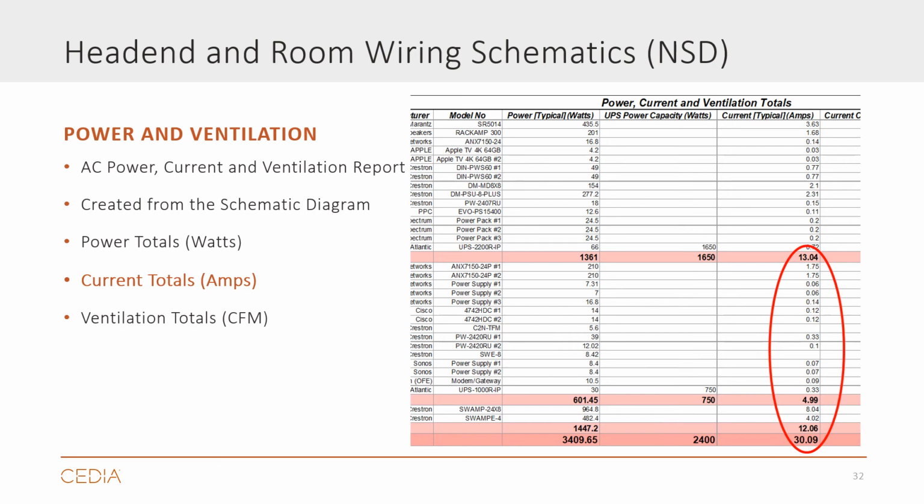So we see here the total needed current for the rack is 30 amps. So 3 separate 20 amp circuits will be used here. Providing some AC headroom is always a good thing.